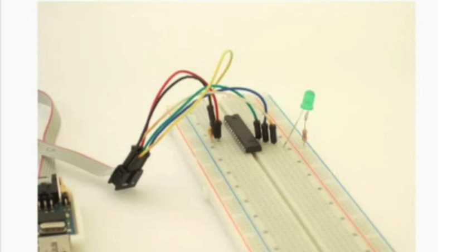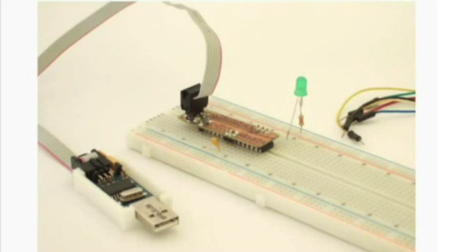You can see this is a little bit of a dodgy arrangement with those 6 pin headers stuck into the cable. Here's what I use every day, something a little bit more refined. This little programming spider just fits right down over the chip and connects those 6 lines up for you. All in one little breadboard. Sweet. I even labeled the pins on it. It's totally handy. You should make something like this for yourself. I have plans for mine up on my GitHub if you are able to make circuit boards or just want to do it yourself.